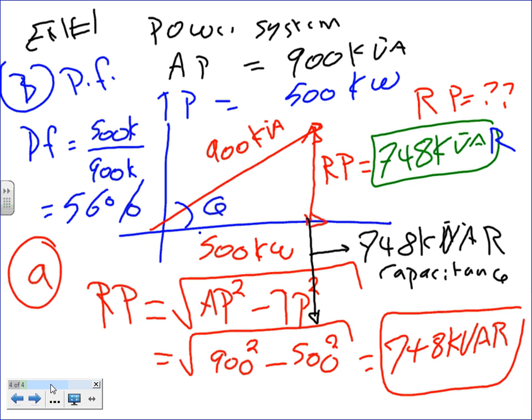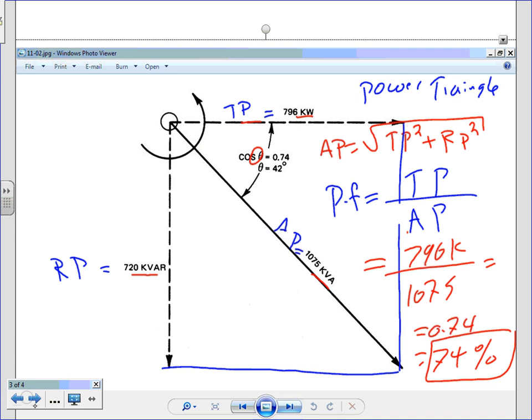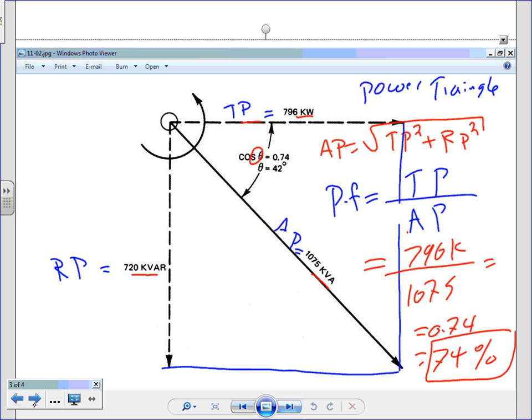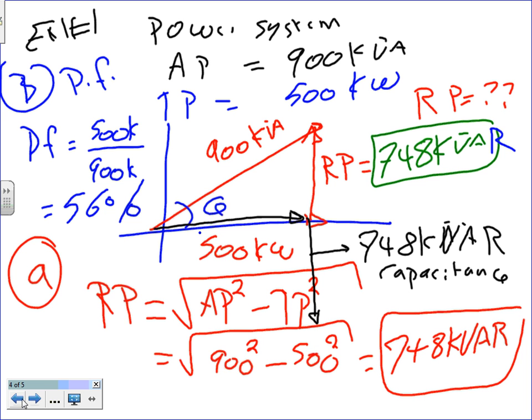They basically add each other to zero. Look at this, 748 pointing down, 748 pointing up. So when they add up, guys, they add up to zero. So the triangle will look something very similar to this. This is your triangle. This is one line. So in a case like this, we have this one. In a case like this, your triangle, after you get corrected, is going to look something like this.